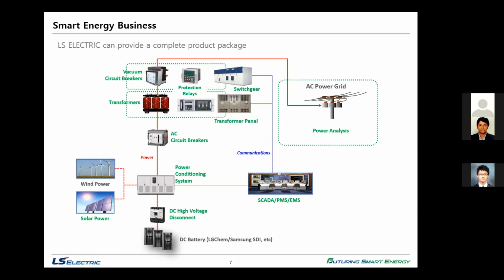So for the battery, we need the BMS. BMS means battery management system. It manages each battery cell. It monitors the voltage and the status of the charging battery cells, makes a balance, protects against overcharging, and communicates with the PMS to protect the switching in case of a short circuit or overload. Here we can see the PMS. PMS means power monitoring system or power management system. It controls voltage and frequency, etc.